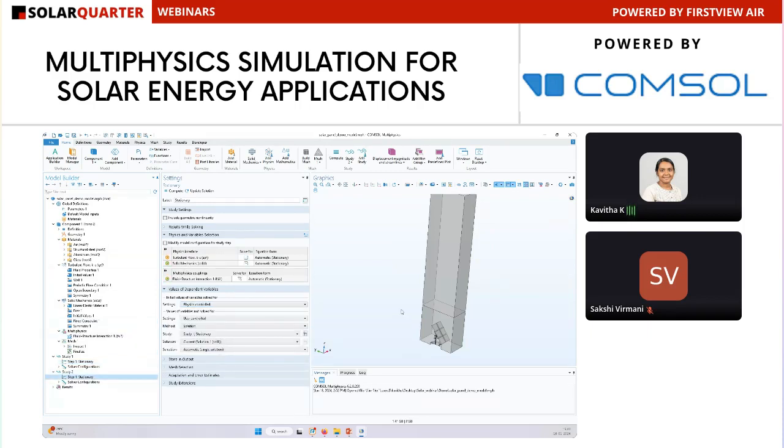So here the wind load will be applied in the solid mechanics model, and you will be computing the stresses and displacement. So once you are done with setting up the physics and setting up the study, then you will click compute to evaluate the result.